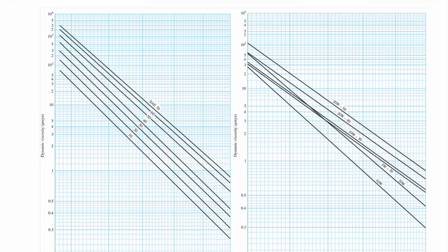If we can come up with a chemical synthetic combination of lubricants that allows us to sort of flatline that gradient, so that when the temperature is colder, you still get a similar viscosity of the oil as when it's hot outside, then that would be advantageous to the performance of the engine. And so that is what this W means in 5W30. When we're in colder conditions, it behaves more like a grade 5 oil, and when we're in warmer conditions, it behaves like a grade 30.